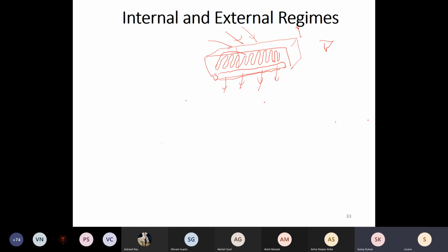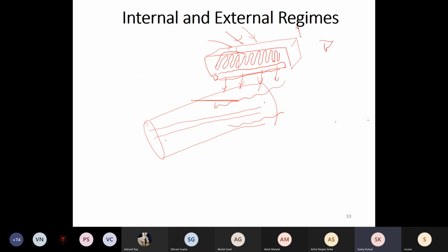So in case of air, if you have to obtain the counter flow arrangement, you will need your evaporator to be in this form. And then maybe in the annular space, if you have a larger diameter, you can blow air through that. And this is the evaporator, with liquid plus vapor refrigerant inside, which comes out as superheated vapor or saturated vapor. This would be the arrangement.